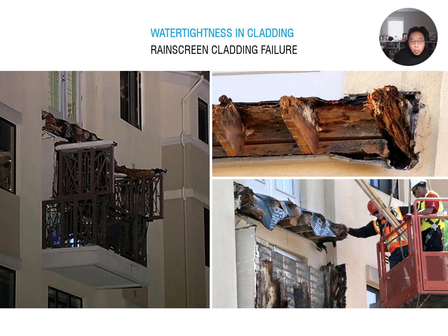Second, and more critically, the wall and balcony assemblage didn't provide sufficient cavity space between the structural component and exterior finish. So it doesn't have any cavity space, any dry air, or any way for moisture and water to escape between the structure and finished material. As a result, water and moisture became trapped within the assemblage. Without proper ventilation, the moisture couldn't escape or dry out.